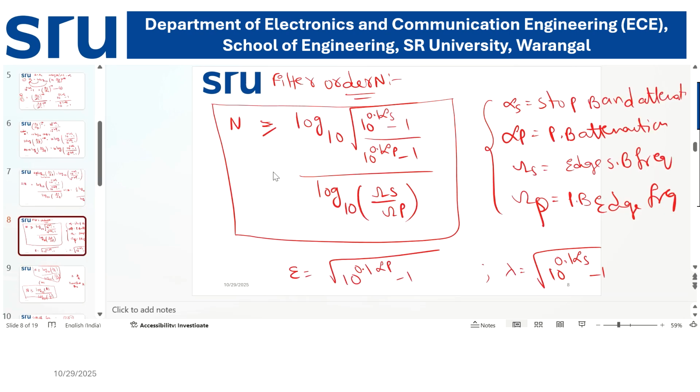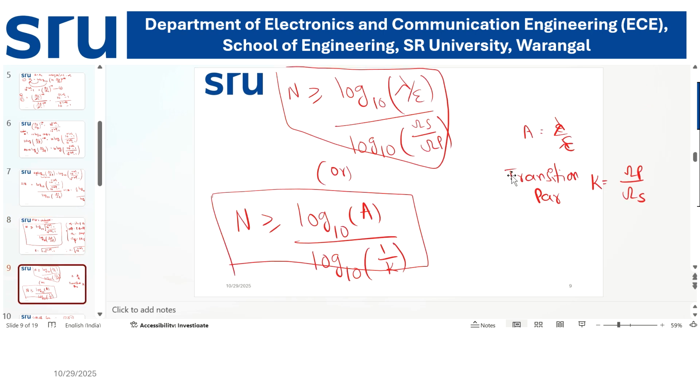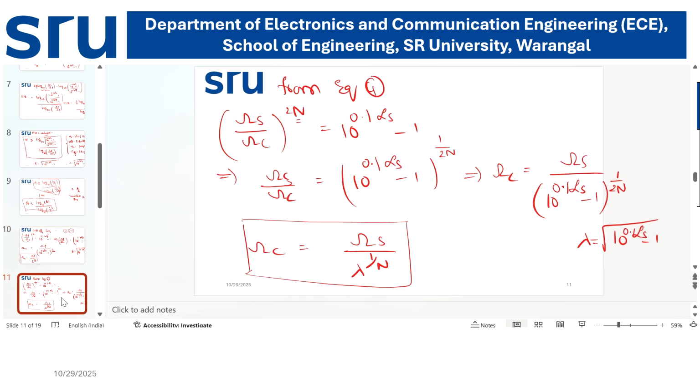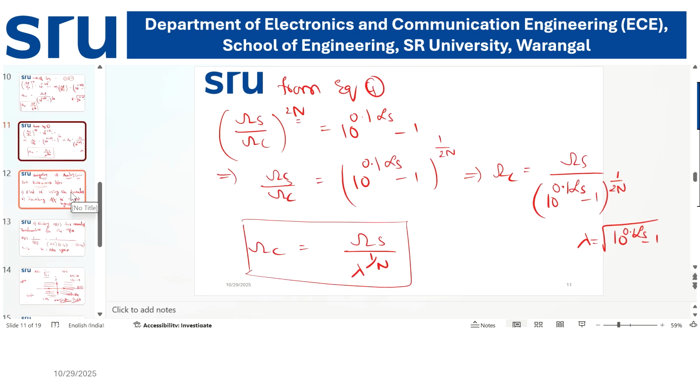The first formula depends upon the passband attenuation, stopband attenuation, passband gain, and passband and stopband frequencies. There we substituted epsilon and omega to simplify the equation, and we got one more formula in terms of gain and the transition parameters. Also we determined the n value. After that, for the cutoff frequency, we considered equation 3 and equation 4. Those equations we substituted to get the cutoff frequency. So this is the exact cutoff frequency we have for the given practical characteristics.